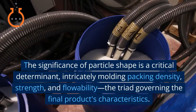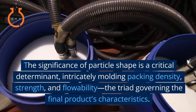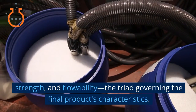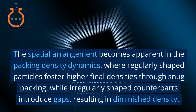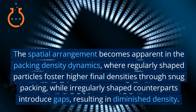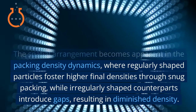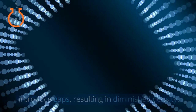Particle shape. The significance of particle shape is a critical determinant, intricately molding packing density, strength, and flowability, the triad governing the final product's characteristics. The spatial arrangement becomes apparent in the packing density dynamics, where regularly shaped particles foster higher final densities through snug packing, while irregularly shaped counterparts introduce gaps, resulting in diminished density.